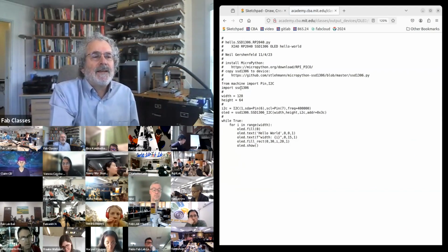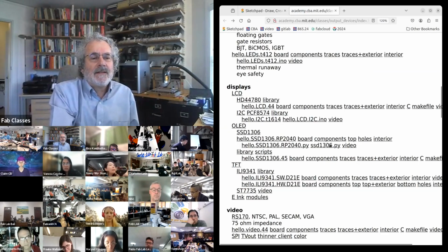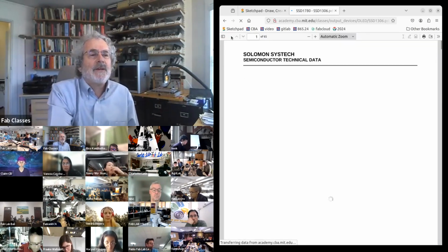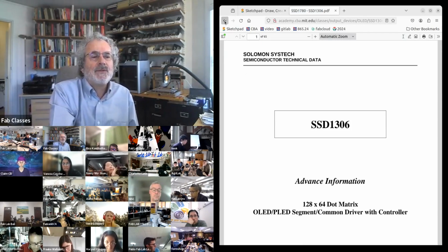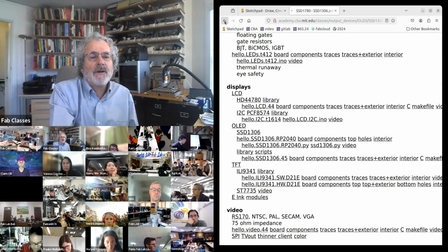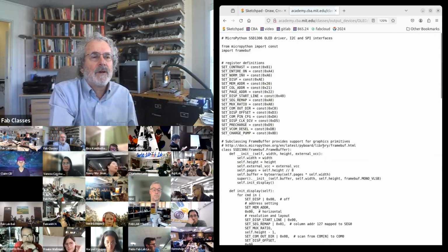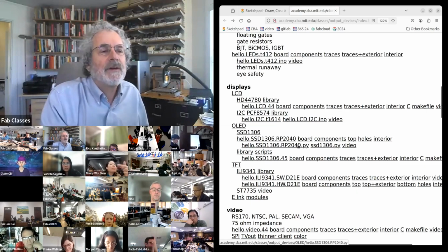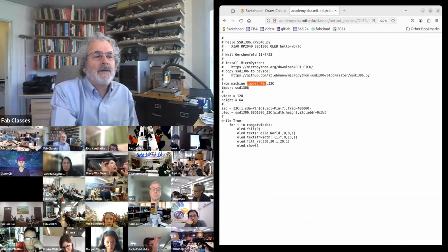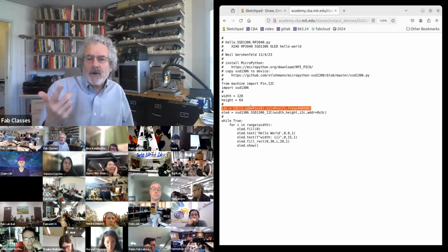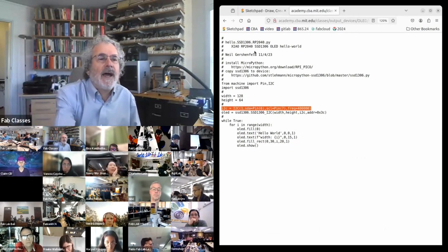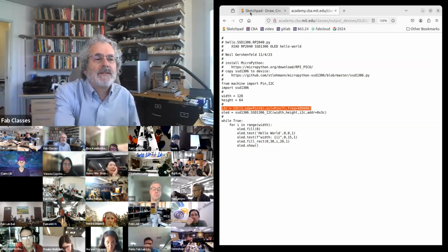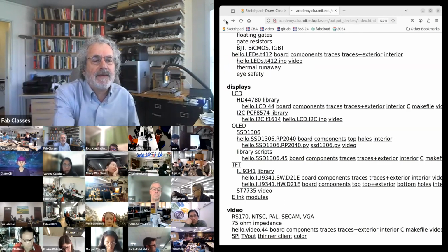I'm using an, let's see, the SSD1306 chip is a common chip used to drive these, and there's libraries. There's multiple libraries for it. Here I'm using a MicroPython library for it. With that library, all it takes is I import the library. I'm connecting it with I2C. I'm going to talk more about this in networking. I2C has 2 pins, SCL and SDA.